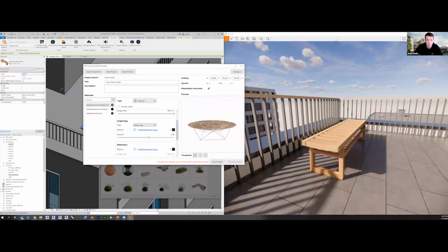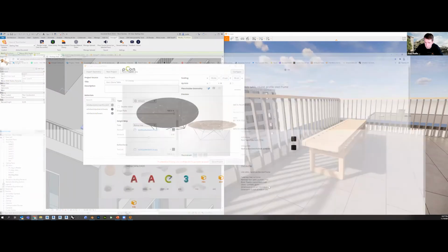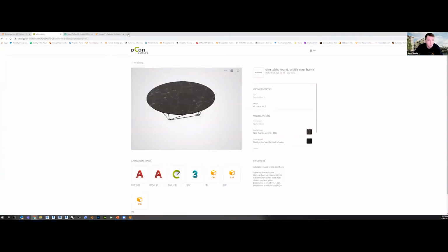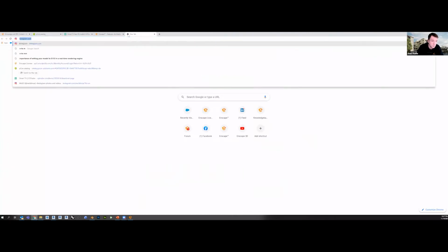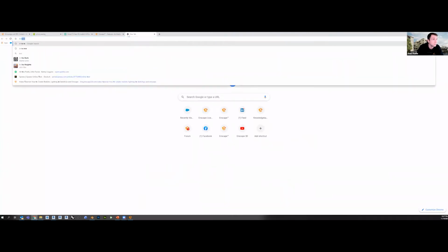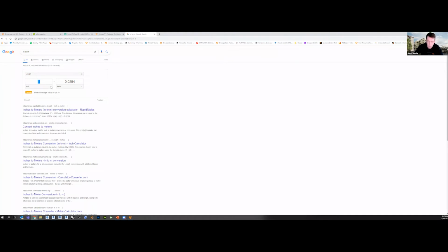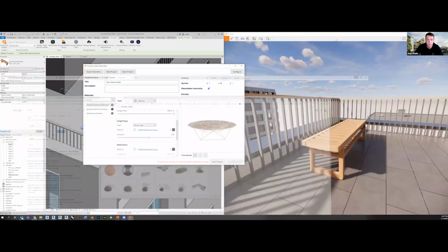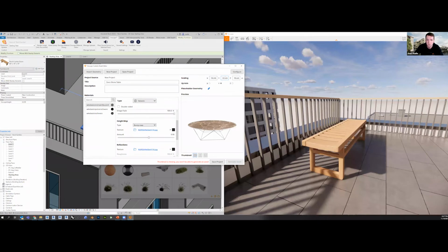It's looking good, but now I need to scale this thing correctly. So right now, this is all in meters. So let me go up to, this is in inches, so 13¼ inches to meters real quick. Let me do 13.25. So it's 0.33. So I'm just going to copy that. And then for the height, yeah, it's pretty close. So I'm just going to move the decimal point over. Now that's automatically going to scale it.